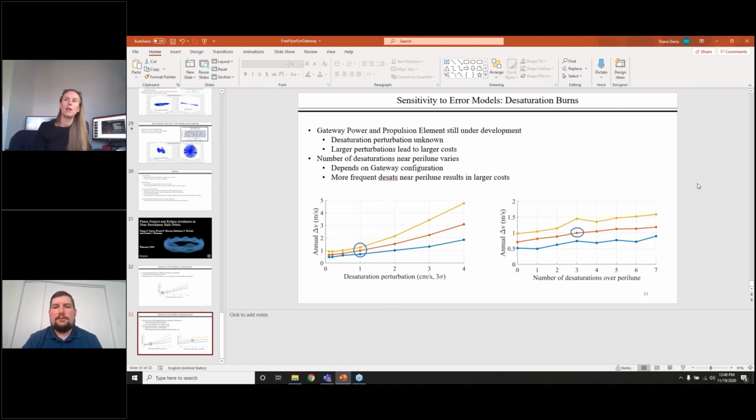Okay, so we have 2 different types of propulsion on the Gateway. We have solar electric propulsion that uses xenon propellant, and we have RCS thrusters that use a biprop chemical thrust. We use both for orbit maintenance. We assume that we use the xenon during uncrewed operations for orbit maintenance because it's much more efficient and we use less prop per meter per second of delta V, for example. If we need to do a burn more quickly, then we do a burn using the RCS prop.